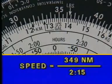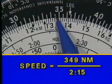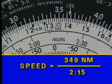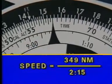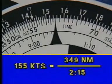For 349 miles, you'll have to estimate the distance from the line representing 345 and the one showing 350. Then you can read your ground speed directly above the speed index mark. In this case, it is 2.5 lines right of the 1.5. By placing the decimal in the correct position, you can determine the ground speed to be 155 knots.